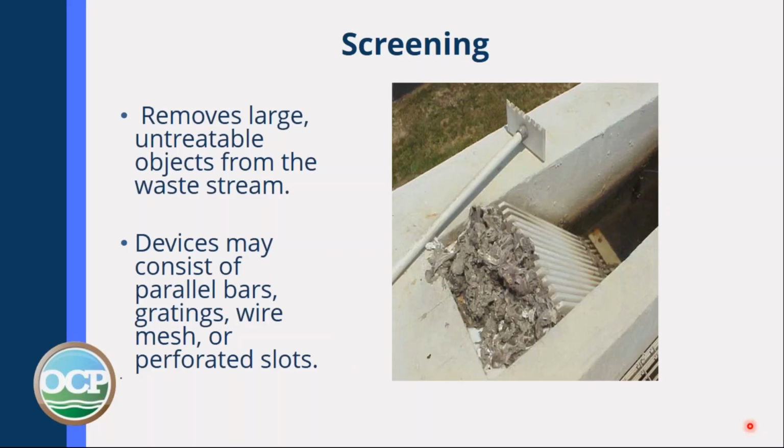So screening, this is probably very familiar to virtually anybody who works in a wastewater plant. As the wastewater comes in, anything large gets caught. You can see here some bars, and you can see here the waste that's been caught in the water coming through. Of course, you're going to have to clean this. There are many different ways that we can do this. We can have bars like this. We can have a wire mesh. The next couple of slides will show some things that we might encounter.